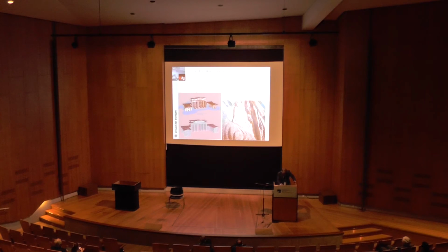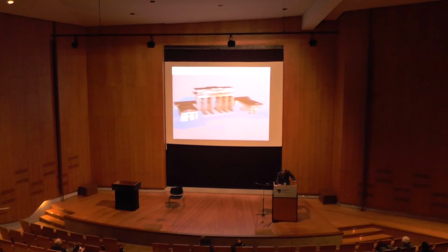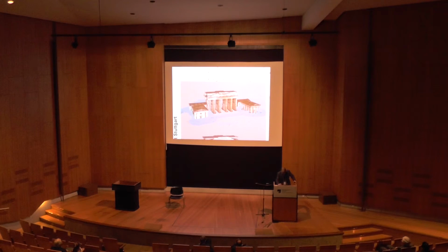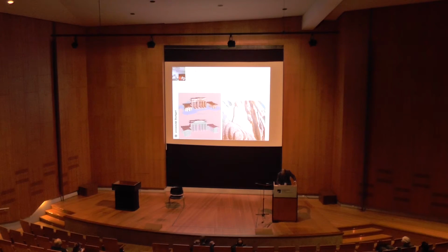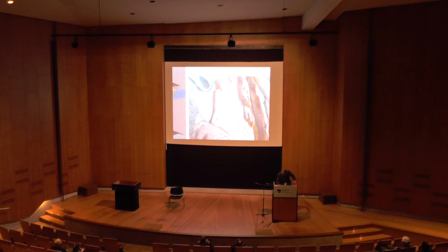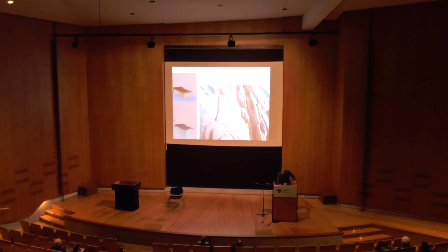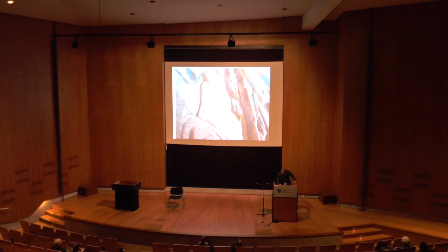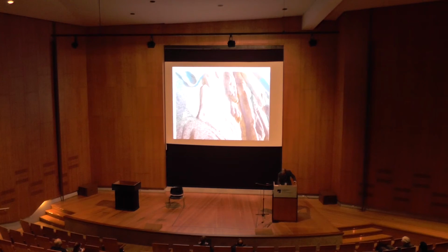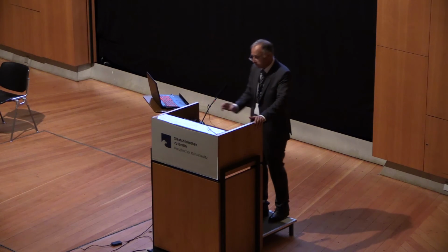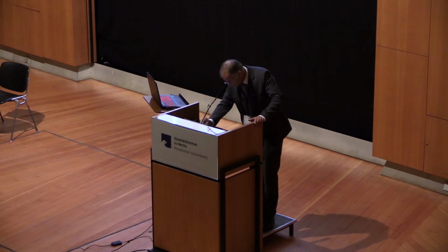We used dense image matching, and you see here already the result of the reconstruction, which looks quite nice, and those blue markers just indicate all the photos which have been taken. And what might be interesting for you is this relief was reconstructed using a zoom lens, this object was at a distance of 10 meters, and you see all the details of this sculpture on the Brandenburg Gate in excellent quality.